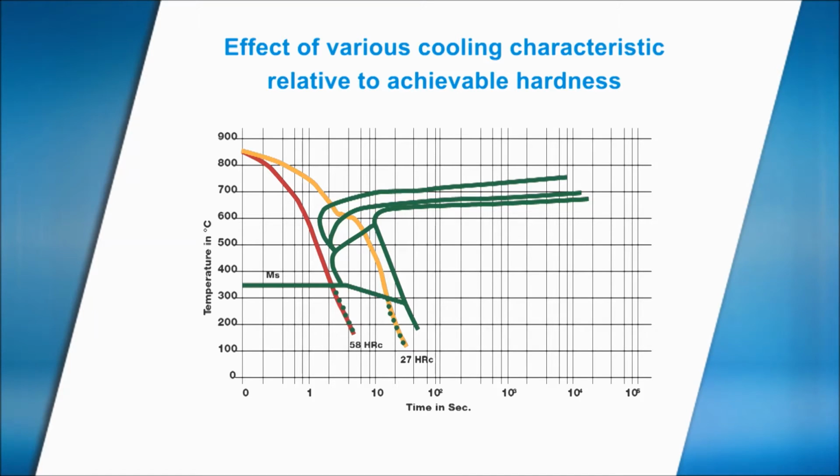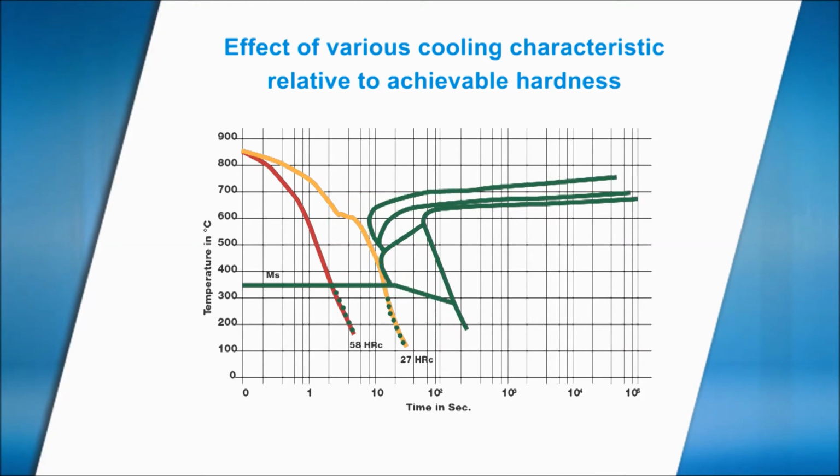For the hardening of alloy steels, where the TTT curve lies further to the right, the duration of the vapor phase is less critical. But one should also consider that uniform cooling of the surface reduces thermal stress and distortion, as discussed earlier.